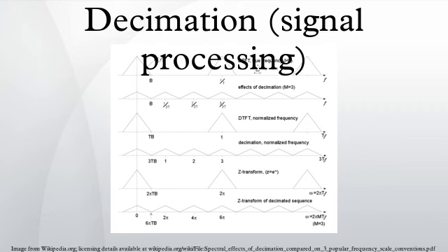When the anti-aliasing filter is an IIR design, it relies on feedback from output to input, prior to the downsampling step. With FIR filtering, it is an easy matter to compute only every Mth output. The calculation performed by a decimating FIR filter for the nth output sample is a dot product, where the h sequence is the impulse response, and K is its length. x represents the input sequence being downsampled.